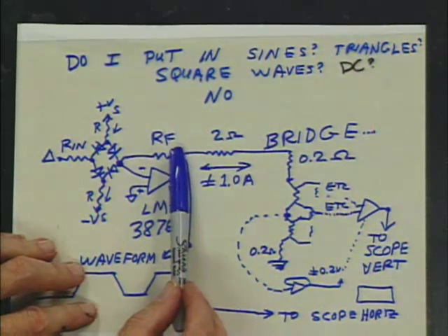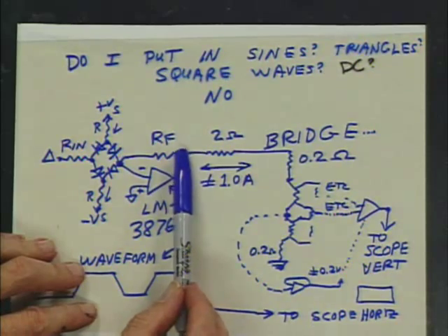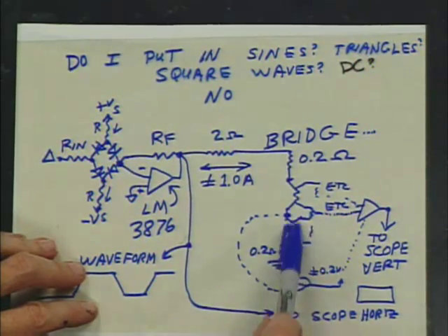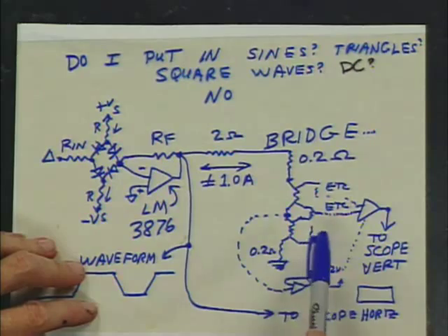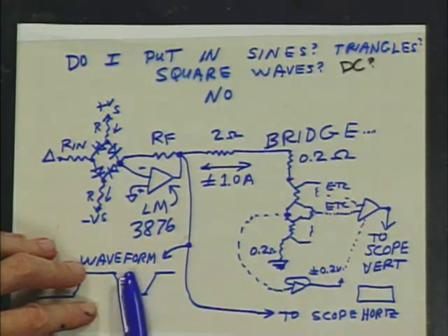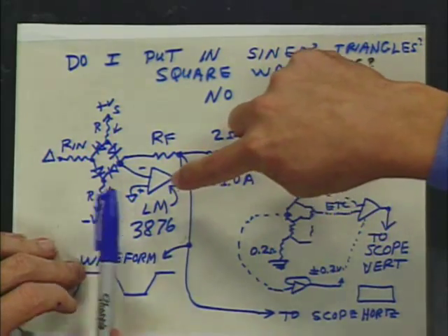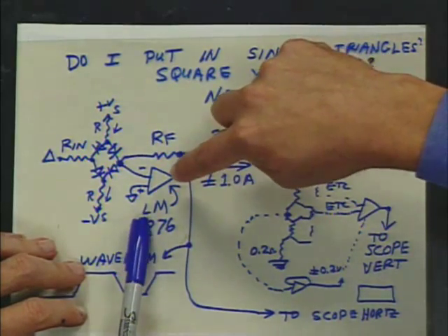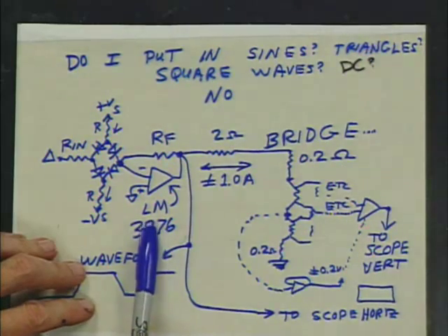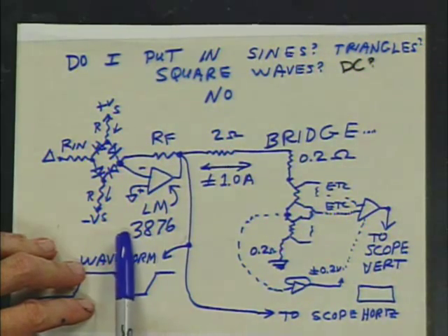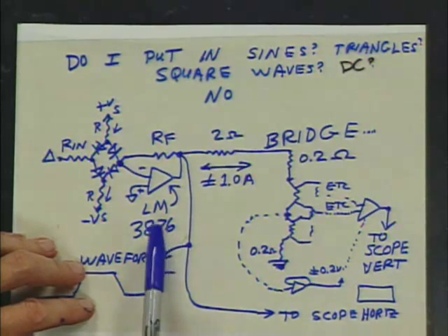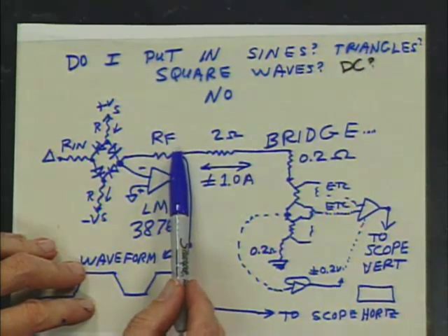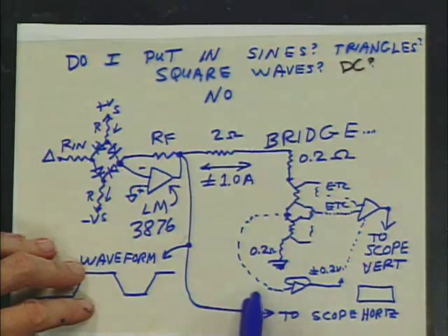And this will be at minus 2 volts with 2 ohms and a current that runs through here. And all this stuff is running as a well-balanced circuit. So you're using an audio amplifier as a DC power amp. Absolutely. I'm using the LM3876 to provide excellent DC current gain to provide this 1 ampere until the whole thing runs very stably.